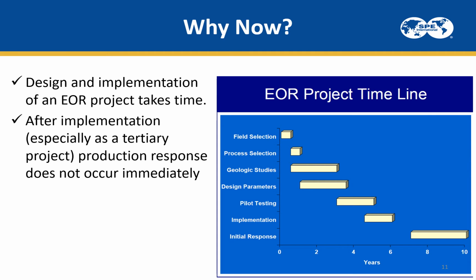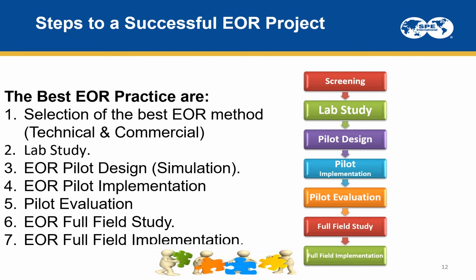As an example, this is from SPE, the EOR project timeline, starting from field selection, process, geological study, designing of the volumetrics, pilot testing, implementation, and then you can get a response. All of these stages will take almost about 10 years to get the response and to get an indication of the success or failure of this EOR method. So EOR should be considered as early as possible.